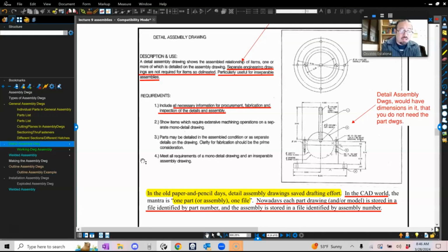When you go and cut into this assembly to see other parts, because they are internal parts, you are not supposed to have participation in the section for these bolts. You're not supposed to section the bolts or the washers or the nuts.